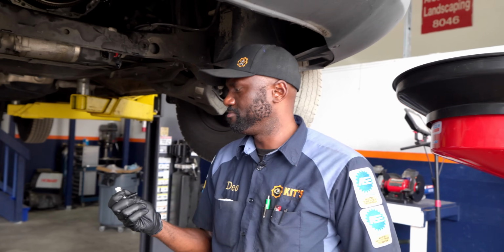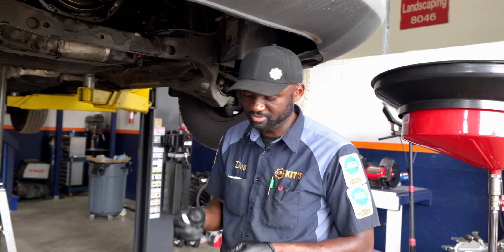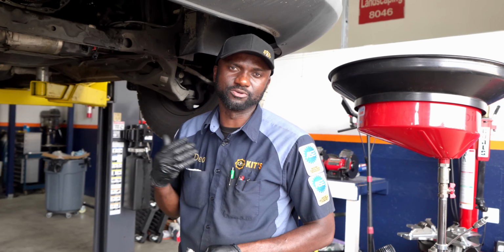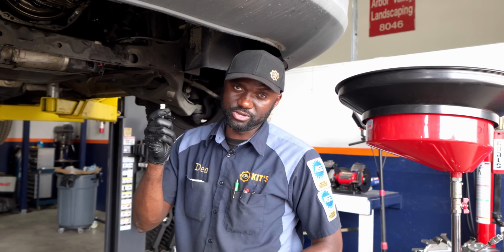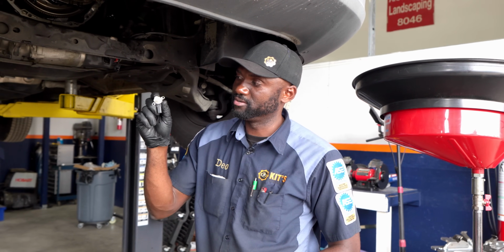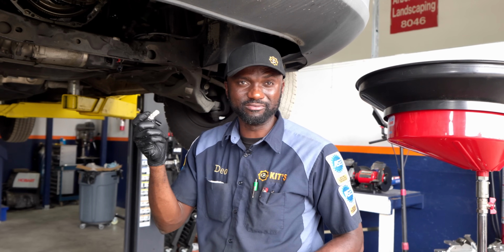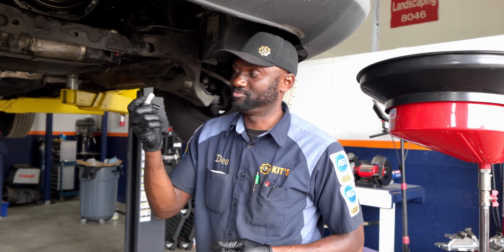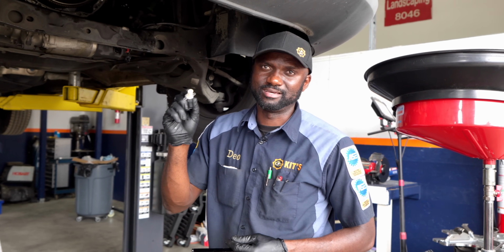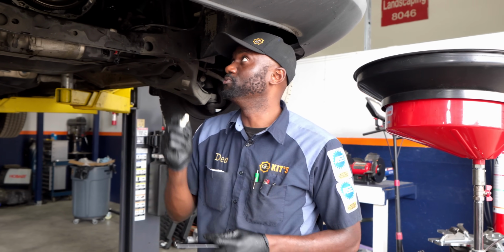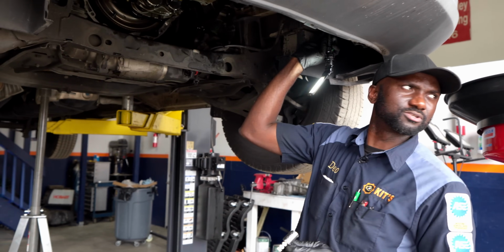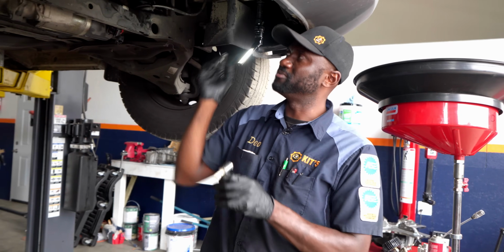So based on the numbers that we saw on the multimeter screen, that once again confirms to me that we made the right call. The old solenoid was bad. As you can see, the new one only has a resistance of 12 ohms, but the old one was almost 3 times more than the new one. So we made the right call. After we install all these components, this is going to be fixed.